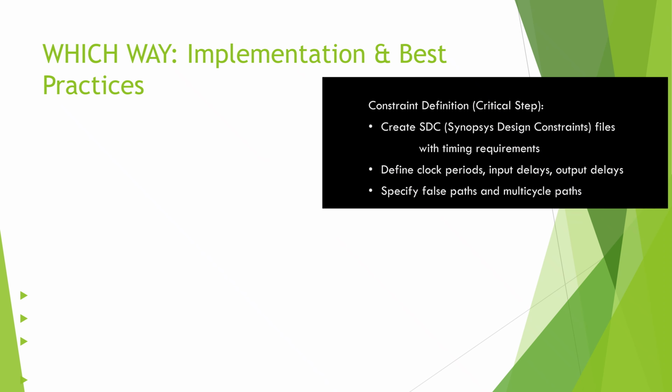One very important topic is constraints, especially SDC. The Synopsys Design Constraints file tells the tool exactly what timing requirements and special paths it should consider. In SDC, you define clocks, their periods and waveforms, input and output delays, generated clocks, virtual clocks, false paths, and multi-cycle paths. So SDC is like the tool's rulebook and contract.